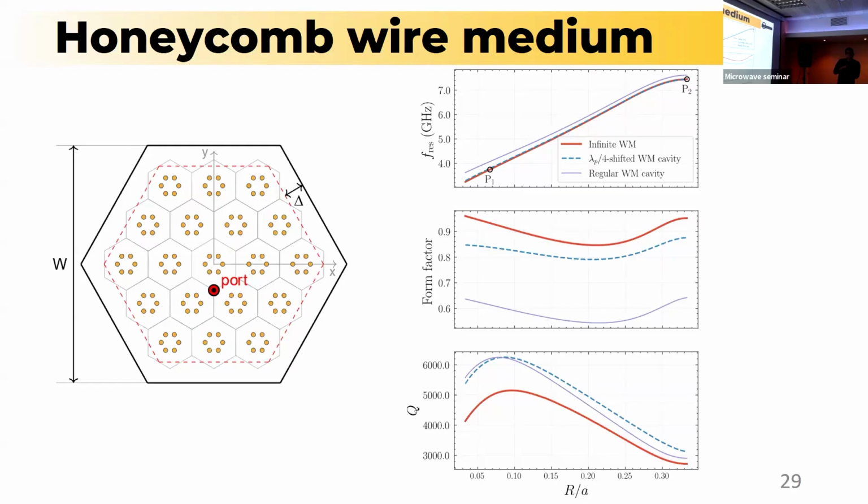The energy dissipated in this case looks evident because we have the wires, so we have some currents flowing through the wires, and there will be some power dissipated due to those wires. In the cavities, it's more evident because we have the power stored. We actually calculated analytically for the rectangular cavity, and we can get some results that can be compared with numerics.